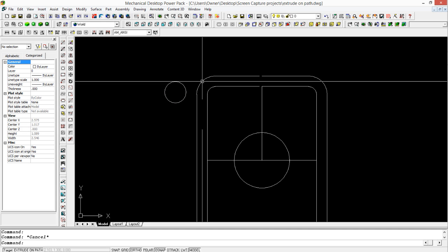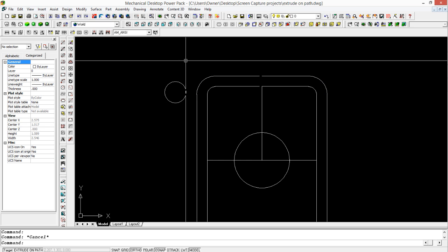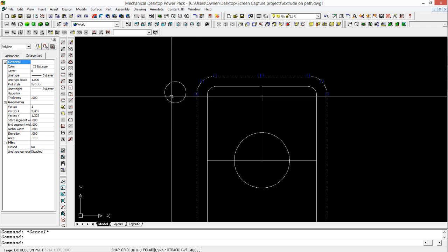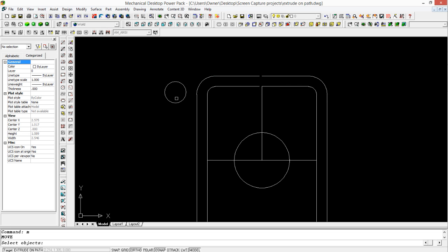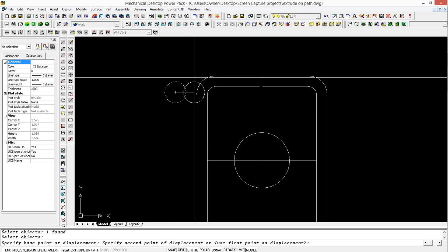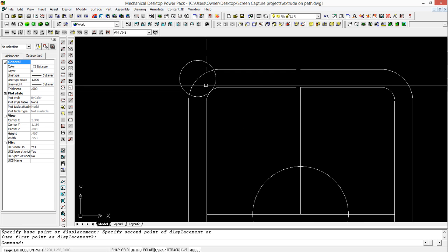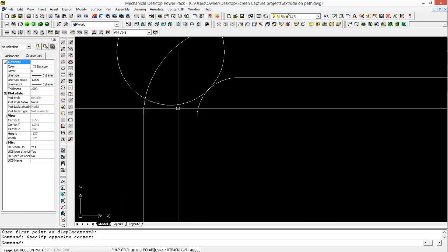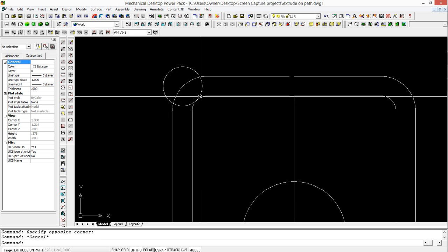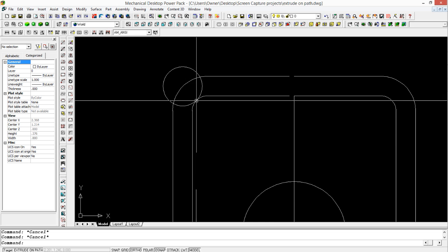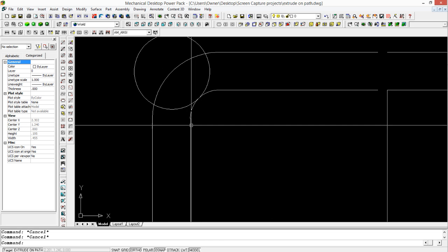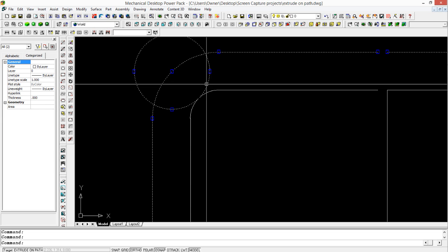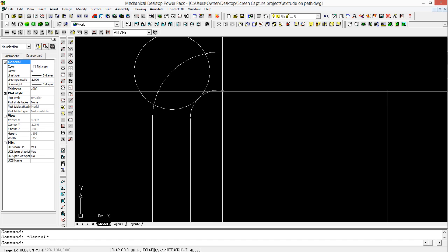Well, the curve right here, this curved area, has to have a wider radius than the object that you're trying to sweep. And you can see I've drawn this in that this point distance here is 0.04, and so you can see we still have a curve on the inside. If this object were to sweep this path right here, this is what that inside curve would look like.